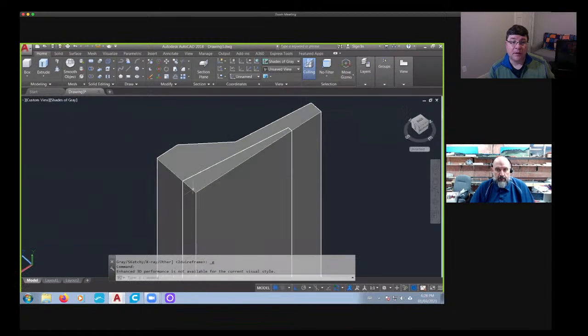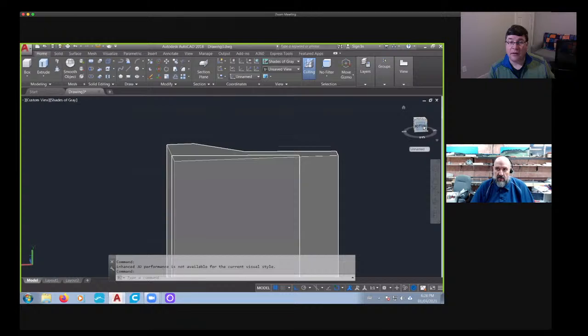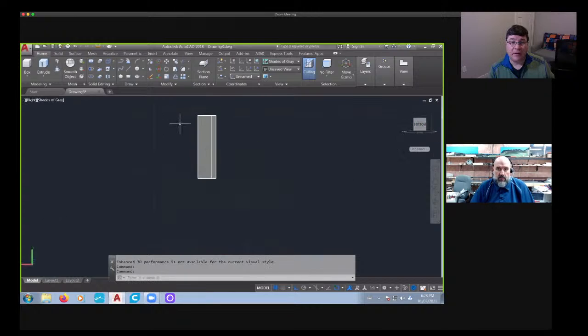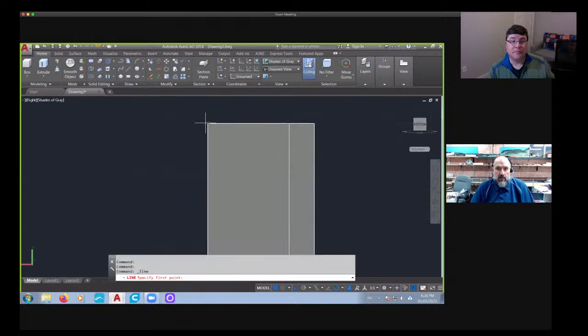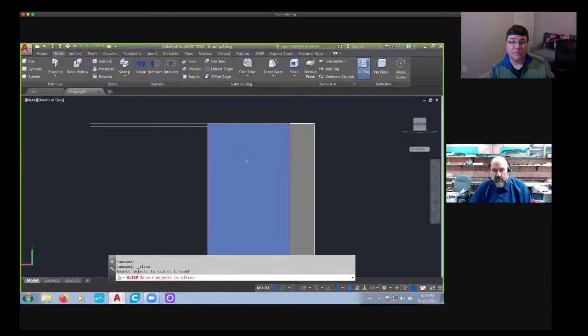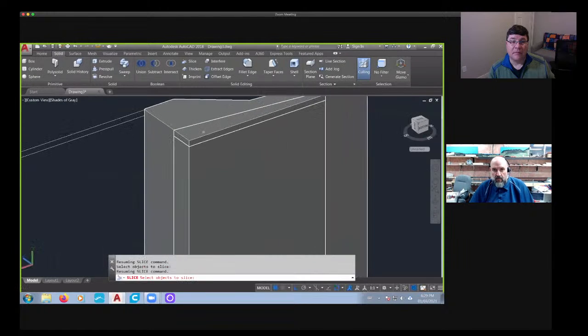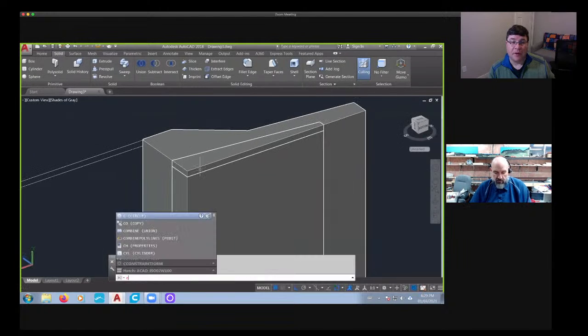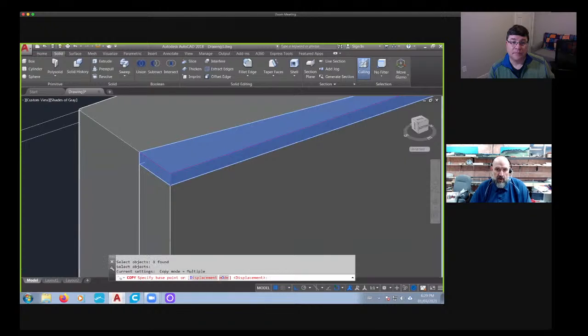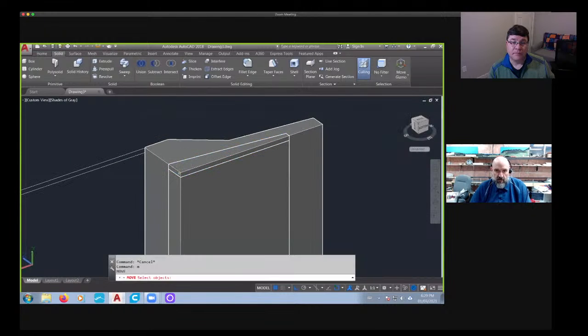One way to do it, which is pretty easy, is I can slice it. I'll do it a couple of different ways. So I can go work line, offset 0.3, solid slice here, and then straight over. And this becomes our bump out. So you can go ahead and move this in this direction.